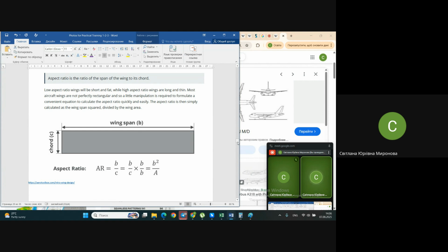Besides the wing aspect ratio that shows additional elongation, we have one more coefficient that shows the wing's conditional narrowing, in case you're going to use a wing of swept shape or of tapered shape. Also do analyze it, and next use the same relative parameters. Your area of the wing may differ depending on the variations, let's say, in the statistics that you have collected. So sizes like wingspan will not be quite the same. You understand it? Yes?